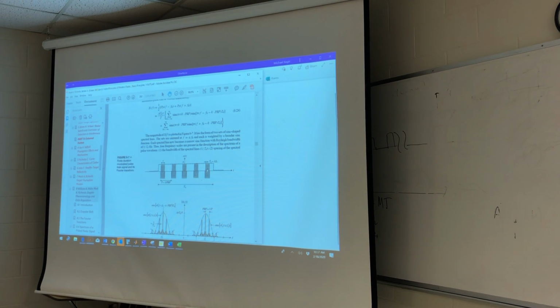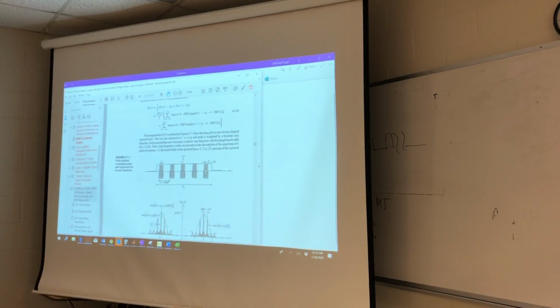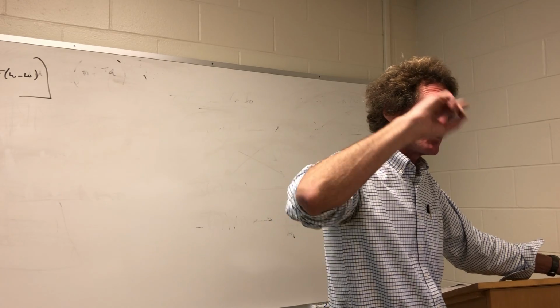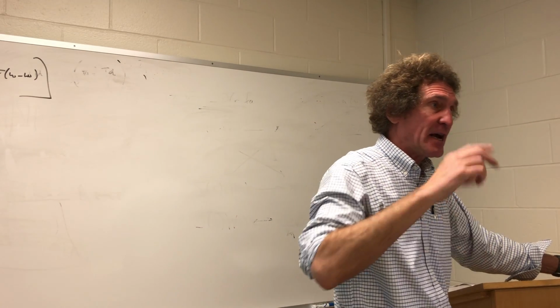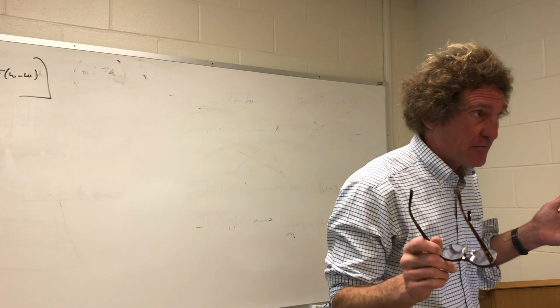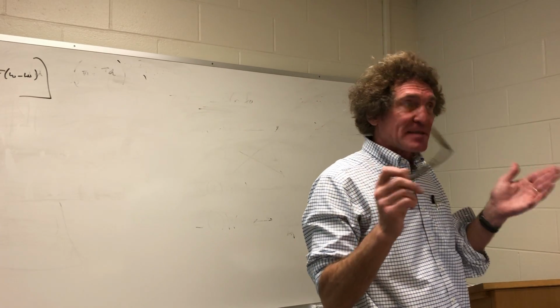So you have to have over 100 cycles for the actual impedance of the antenna you transmit on to look at it as if it's a continuous time wave. If you don't have a whole lot of cycles feeding that antenna, you just get a transient response from the antenna. So you have to have a lot of cycles in order for it to act like an antenna at that frequency F0. Follow me? It can't be one cycle. It'll look like a transient.